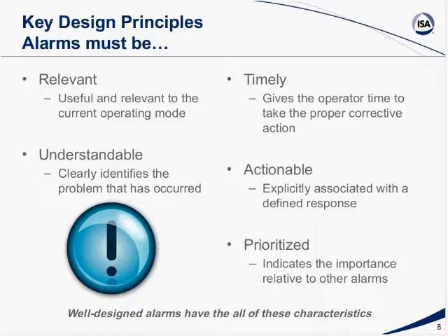Alarms must be relevant. They have to be useful to the current operating mode, okay? They have to be understandable. Not understandable to the person who configures the alarm, understandable to the operator who has to deal with the alarm. And it has to clearly identify that something has happened and that an action is required, okay? Alarms need to be timely, and you have to give the operator time to take the proper corrective action. And one of the things that we will talk about is how you can modify the time an operator has to respond by adjusting the set point for a given alarm.